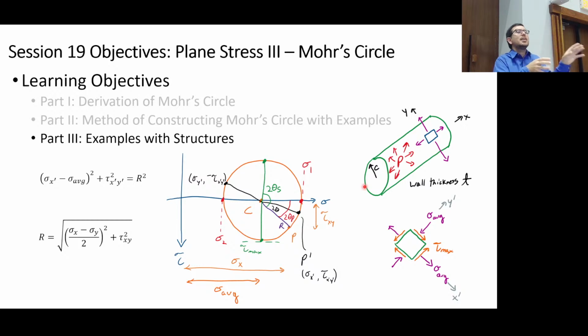Then we combined the loads, right? And we said, oh, at that location A, you can have a sigma x equals this and a tau xy equal to this, right? And now we're saying, oh, we can take those sigma x's and tau xy's and sigma y's, throw them into transformations to figure out what the principal stresses might be, what orientation might correspond to that, and also what the maximum in-plane shear stresses might be, and what the orientation of the element would be there.